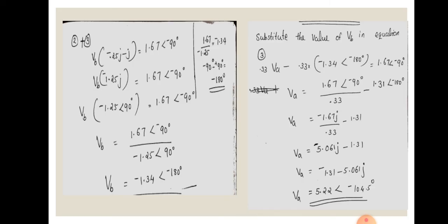So there is no difficulty in doing this problem because the procedures are the same. The only difference is that here we are using AC sources. So we have to consider the impedance term, and it will be in the polar representation or rectangular form. So you have to do the calculation on that polar form or rectangular form. That's the only thing.